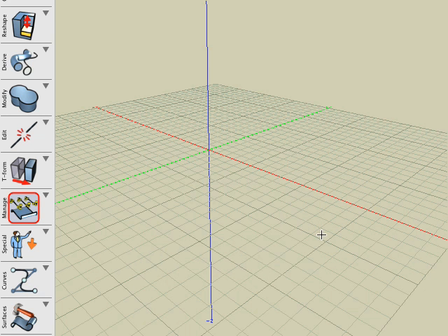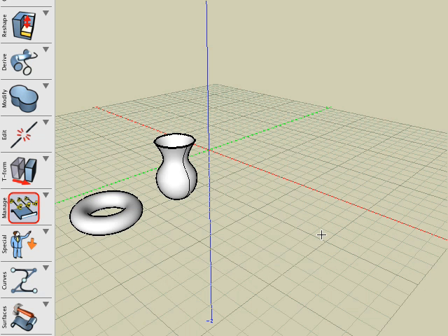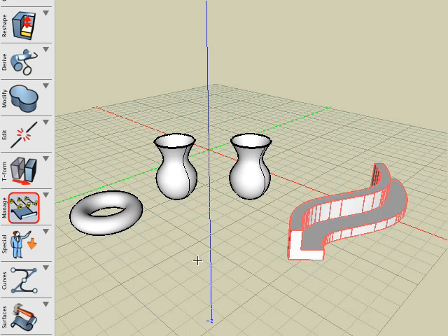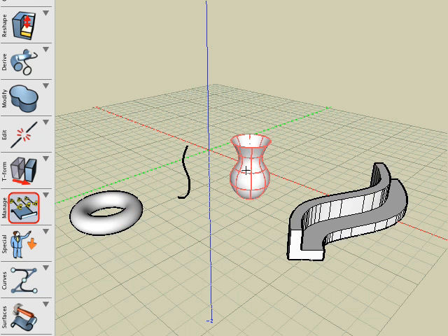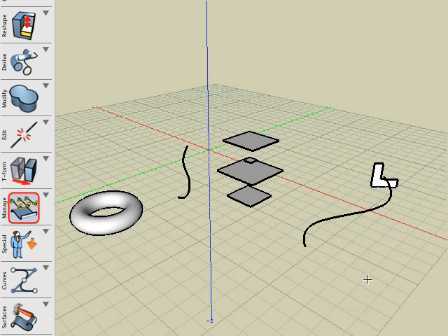We have 4 objects: a torus, a revolved object, a Nurbs object, and a swept object. With the Extract Controls tool selected, click on each of them and observe the result. The torus has no controls because nothing happened when you clicked on it. As for the remaining objects, the Extract Controls tool extracted their original source shapes.